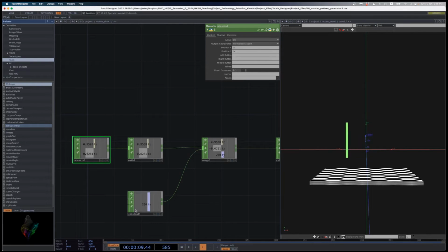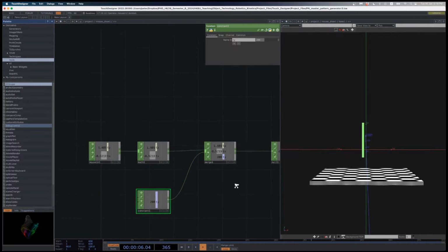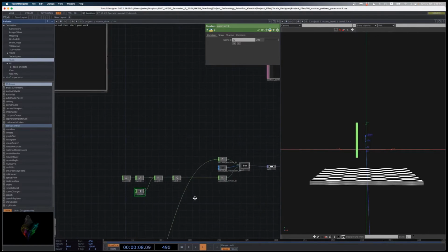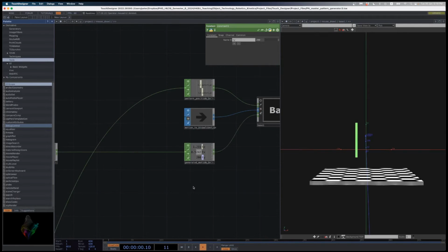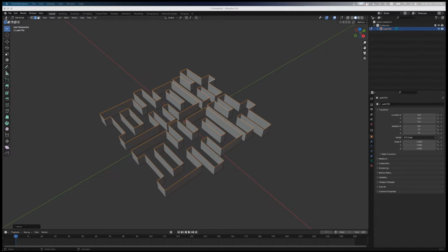At the moment I've left it nice and high, but of course we can drop it down to 150, 100, and so on. Remember that it really depends on what tool we have in there and what that height is. I leave it at 200 because that's a pretty safe bet that we're not going to hit the table.